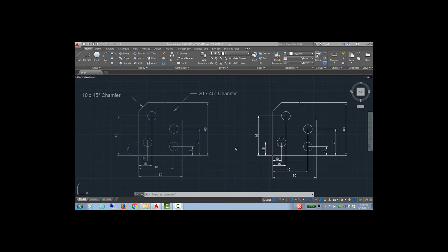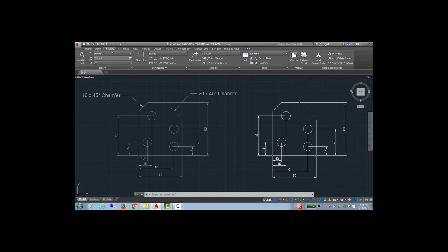Actually, we're not quite finished yet. We haven't put these annotations on the drawing, and the center marks here, so we have to do that. This Home tab provides access to the most commonly used tools, but we want to annotate a little bit more than what is available here. So we'll click on annotate up here, like so. Then we can use the multi-leader tool to create this text here.